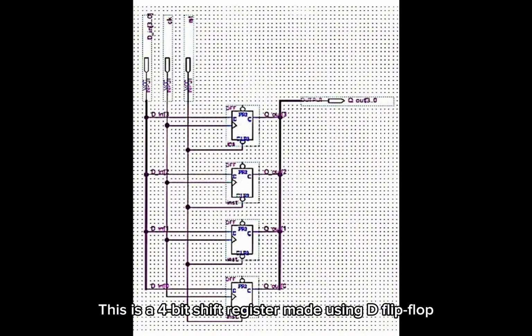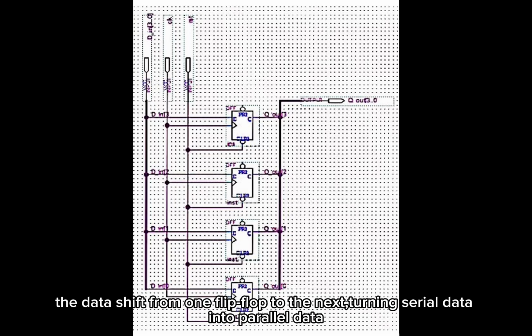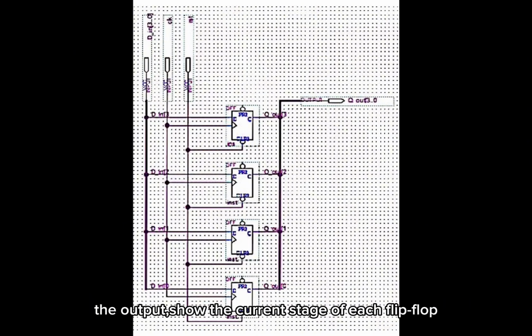This is a 4-bit shift register made using D flip-flops. Each flip-flop receives input from the one before it. With the first flip-flop connected to the external input D-in, with every clock pulse, the data shifts from one flip-flop to the next, turning serial data into parallel data. The output shows the current state of each flip-flop. This type of circuit is commonly used for temporary data storage, bit shifting, and serial communication in digital systems.